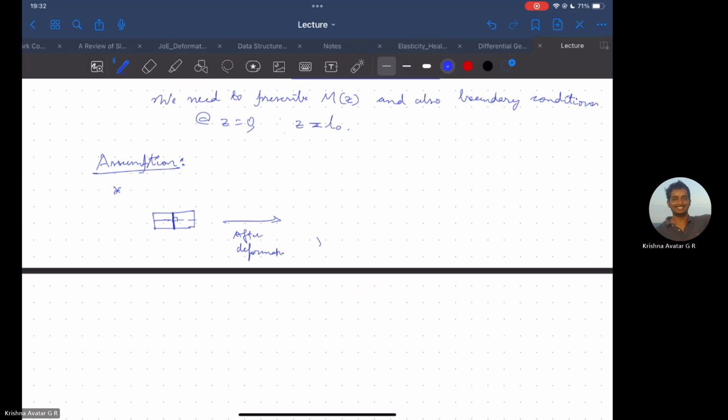After deformation, this linear segment would bend in some form, and you have the center line. Recall that the length of the center line is not allowed to change. Generally speaking, we keep it constant. That's the reason we call it the central line, or also the neutral axis, which does not undergo any tension or compression. The cross section at the same point will still remain perpendicular.